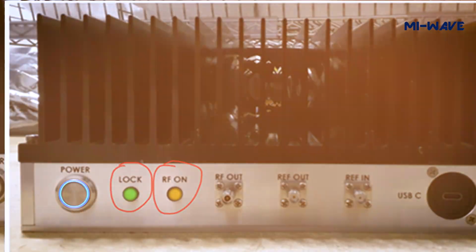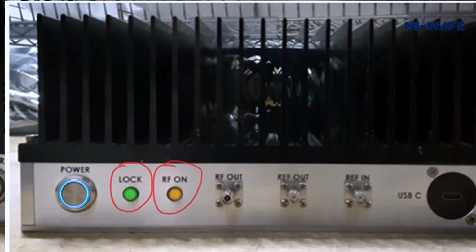Disconnecting the GUI does not disable the RF output. The synthesizer will continue operating with the last program settings. The RF on button activates the RF output. When RF is enabled, the lock LED turns green after the PLL lock. The RF on LED turns orange, and TTL outputs become active.